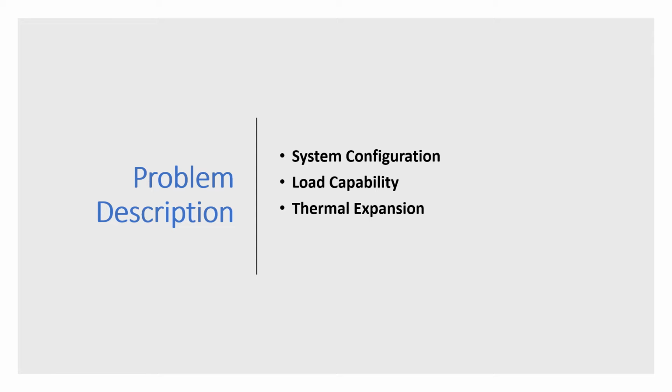Since you are working close to a very hot, very large source of heat, that is a furnace, we need to factor in thermal expansion of the robot. If thermal expansion is not factored in, there might be a huge error that might occur, or the robot might not even be functional. So this is one of the most important factors in this presentation.